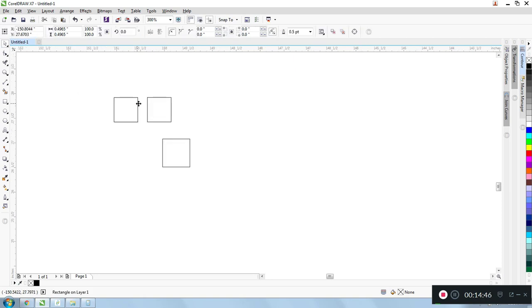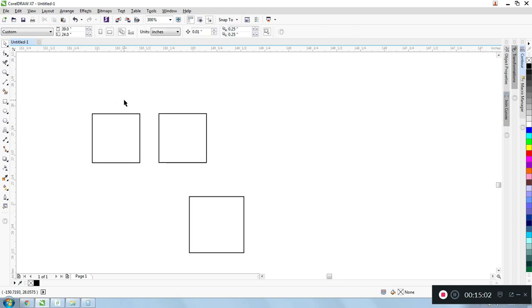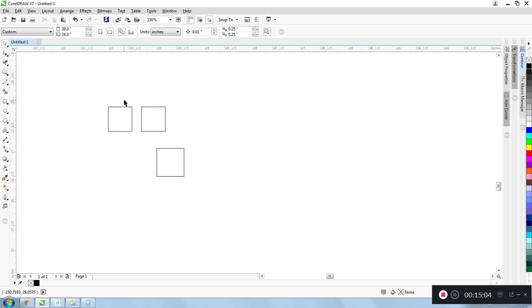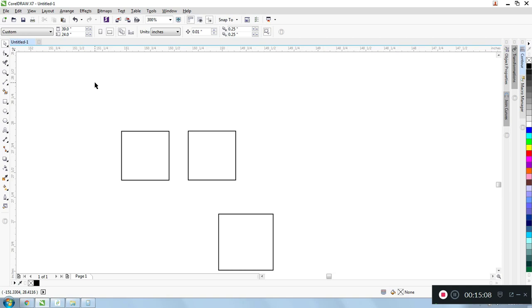Yeah, groups are very important. When you have a bunch of oddly shaped items and they are all nested into something that'll fit on your material, and you don't have stuff grouped and you're trying to move it around and you can't get in there to draw a square around it without grabbing a bunch of other stuff, it's really obnoxious. So just group everything, and when you need to edit it, ungroup it.